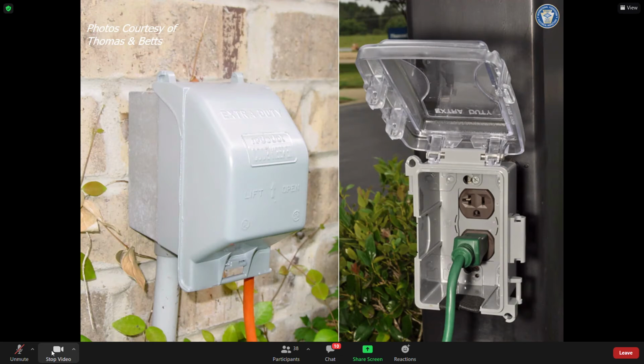What about the outlet itself? That's supposed to be listed WR, right? Correct. You would have to. I don't see any WR. I don't think that it's there, you just can't see it. No, I took that photograph about 5 years ago before that rule came into the code. So it probably doesn't apply then. But it would need to be a weather resistant receptacle. Yes, you're correct, thanks.